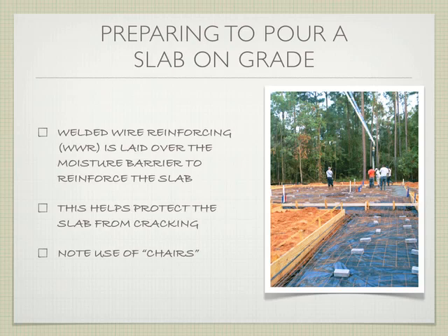And if you have a house that's, say, out in Brentwood or Antioch or one of the new developments that's been built in the last 5 to 10 years, if you look in the garage of your house, there'll be a stamp on the floor saying, "Don't drill in this concrete." It's stamped right on the floor of the garage. So if any of you have these houses, go look. It'll be stamped all over by the door, by every edge of the concrete. That's an indicator that this slab has been post-tension, because if you were to drill in it and hit one of the cables, it would shoot out one side. It's big problems.